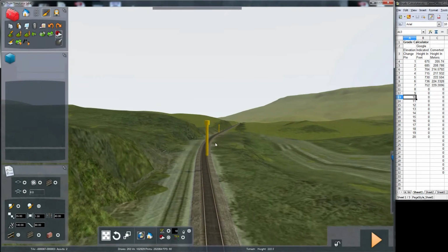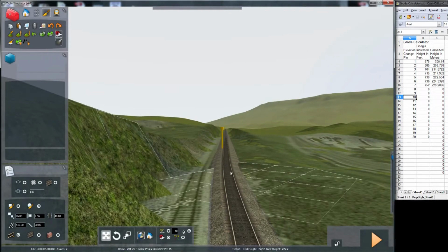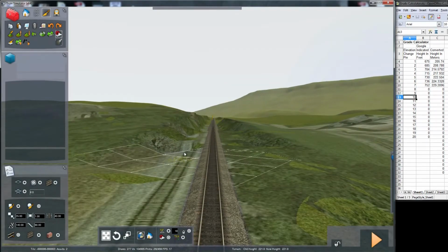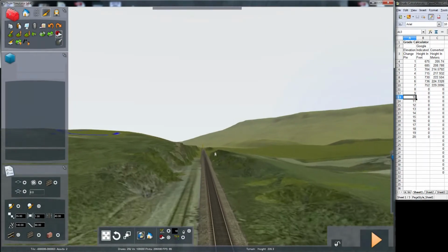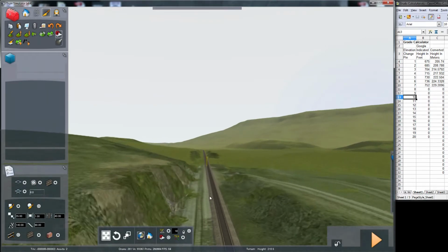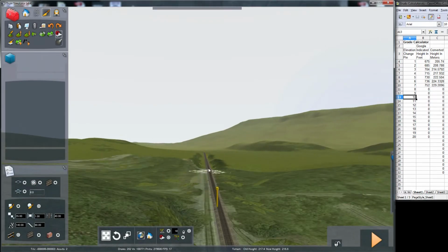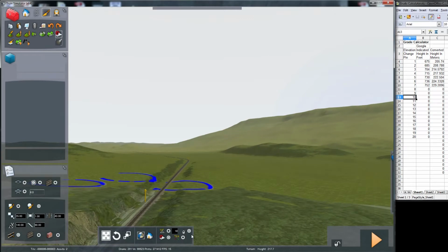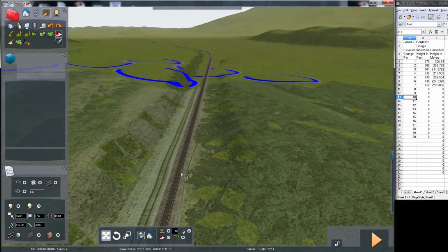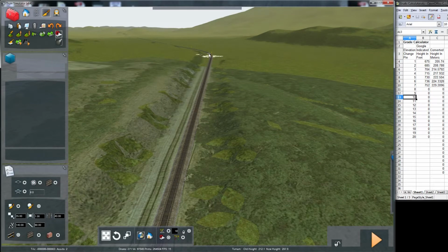We're going to bring it back up to the level of the track. We had a much deeper cut there because the grade changed, and I had left it at 0.9, not knowing what that gradient change was, because I'm working strictly from Google Earth and not a profile chart. When you do use the profile chart, you get much more accurate alignment as you go along, and you don't wind up having to go back over some of this and bring it back up. But it only takes a moment.